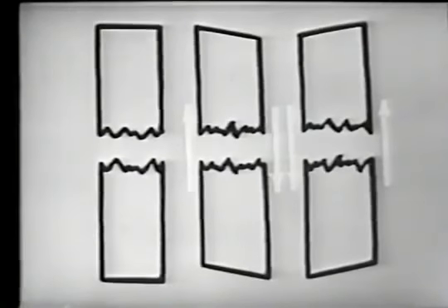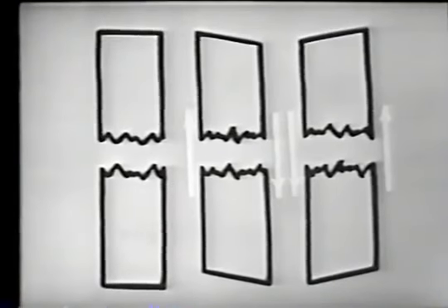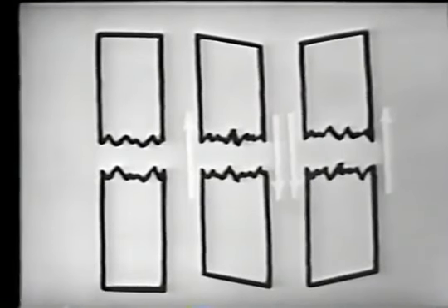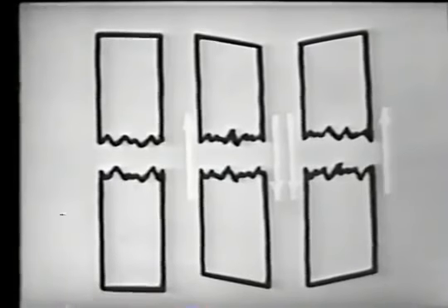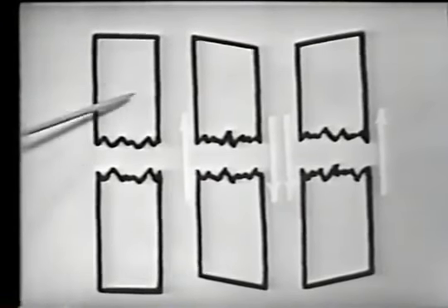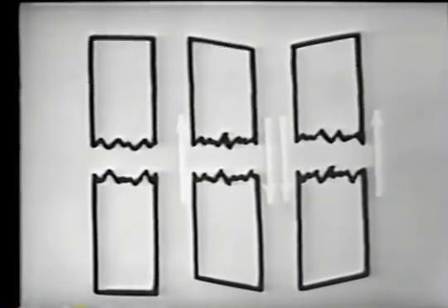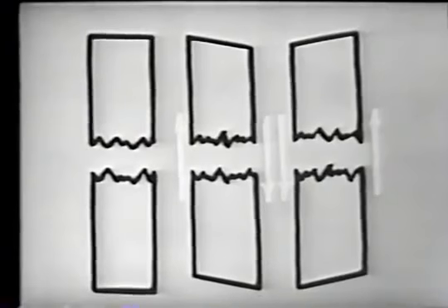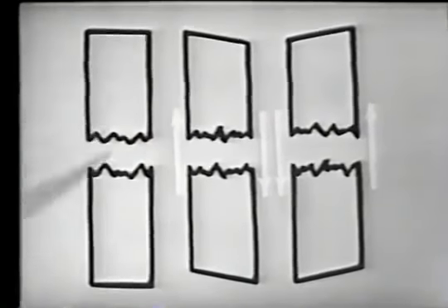You might ask, how is this accomplished? Simply by increasing the feedback to the point where the crystal is shocked into vibrations at the odd harmonic rather than the fundamental frequency. And let's determine what's happening when this is true. Now, here we're indicating the distortions that exist in the crystal when it's oscillating at its fundamental frequency. Here is representing the crystal at rest, no oscillation.